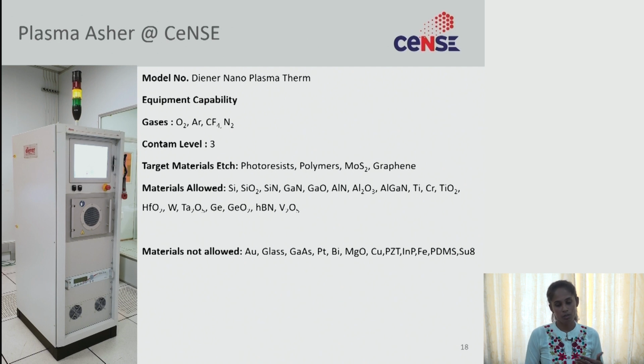This is not only for that. Maybe before you do your etch process, if you want to do some descum process, descum is nothing but using very low power with oxygen gas, we do an O2 descum process. So here what happens is, after your litho process, there might be undeveloped photoresist regions, suppose it has not come out of the solution, it is still there on your substrate.